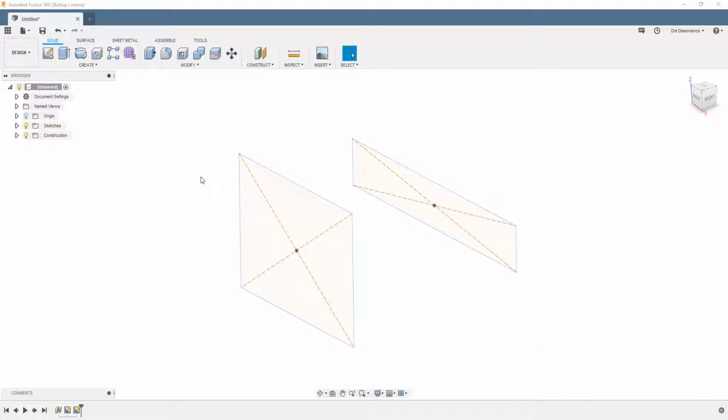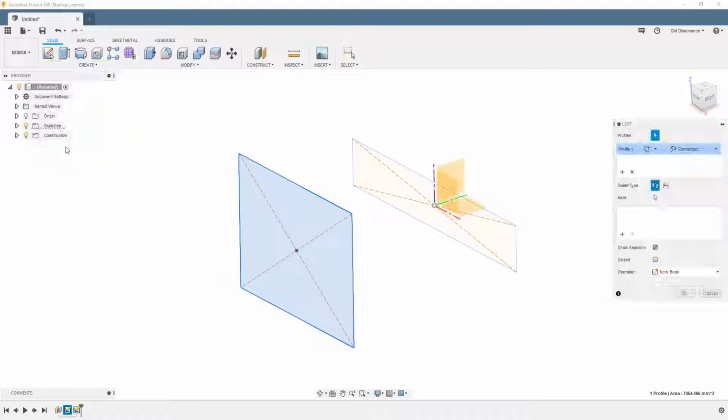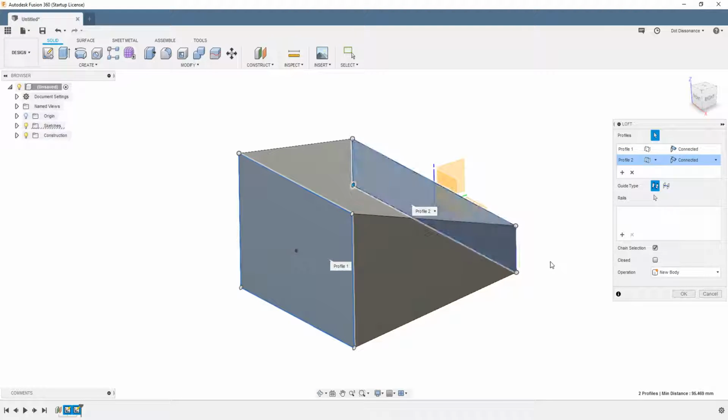Then the last thing I want to do for this video is go back to our basic squares. So now that we know how to do guide rails, now that we know the basic idea how the loft works, what I can do is I can say, well, take this, go to here, connect as normal, but what if I want to create a twist? What if I want to twist this? Well, what I really want to do then is I want to say that this point here doesn't go to that point there. I want this one to go over there, and then I want this one to go down there, etc. Okay, so of course that's going to be Rails.